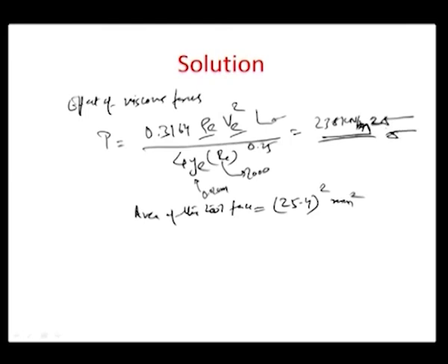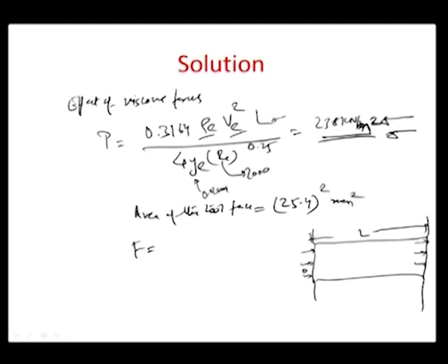and on such a tool face, if such a large pressure of the electrolyte is imparted, the amount of force that the tool face would have is basically, at one side, when the electrolyte has just about entered, the L is 0. So, the pressure is 0, you can think about it as a function of L. So, L is 0 here, and the pressure here is 0, and it increases up to the full pressure value P when L is equal to the full length of traverse of the electrolyte. So, you can assume an average pressure value as pressure here plus pressure here by 2.